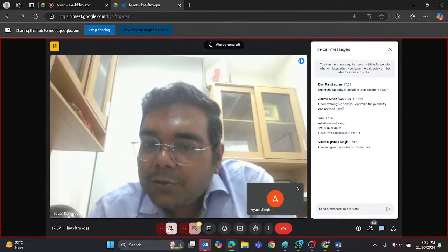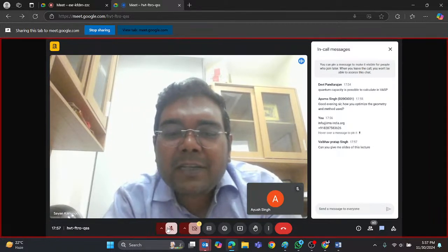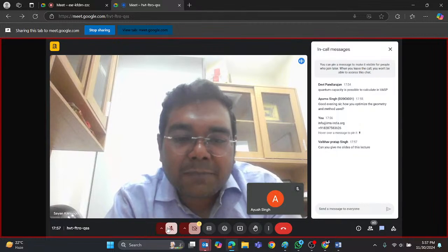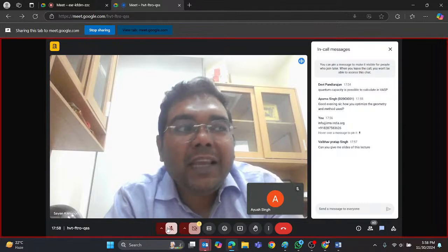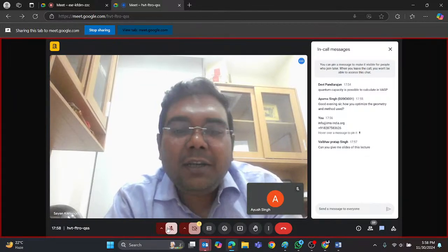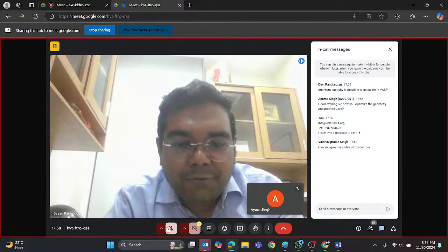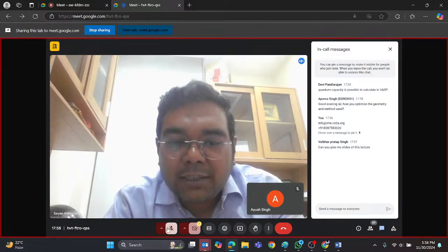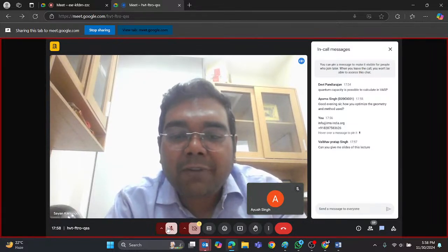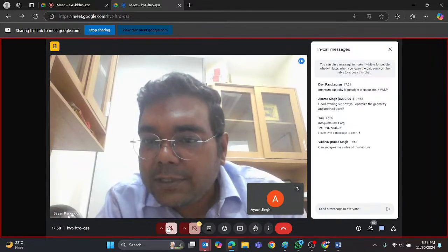Yes, I will address the first one by Aparna, saying, how do you optimize geometry and method used? Geometry optimization is a very standard method for any first principle based calculation. For geometry optimization, basically you have to give the tolerance limit for your material system. Specifically for Quantum ATK, you have to give the pressure tolerance and the force tolerance in your simulation. And also you have to choose a suitable DFT method for optimization. The most standard method you will see in any literature on DFT is the GGA-PBE. I hope that answered the question of Ms. Aparna Singh.